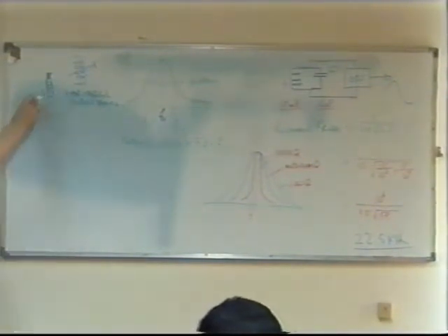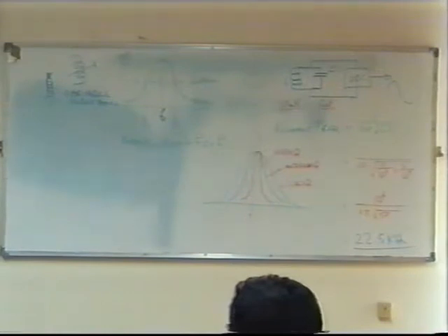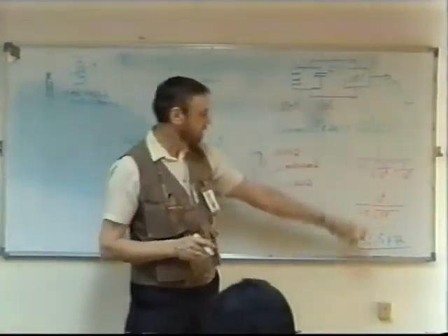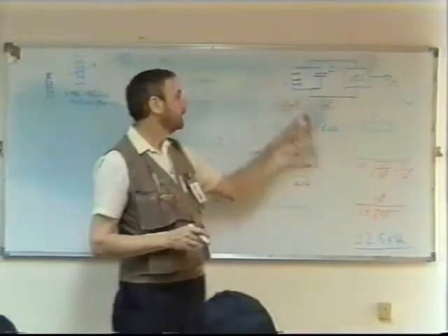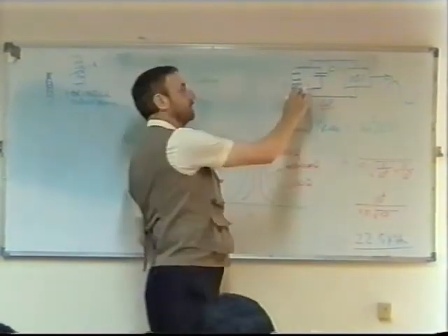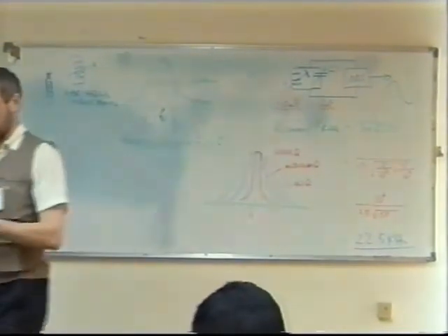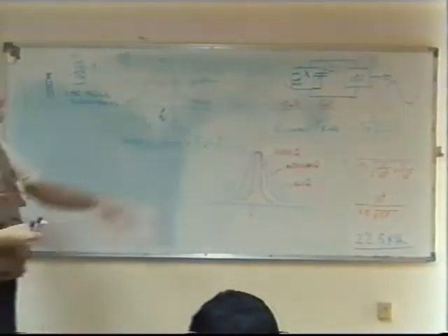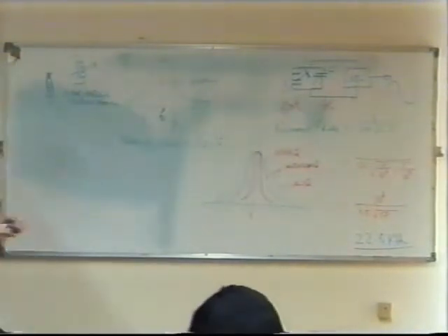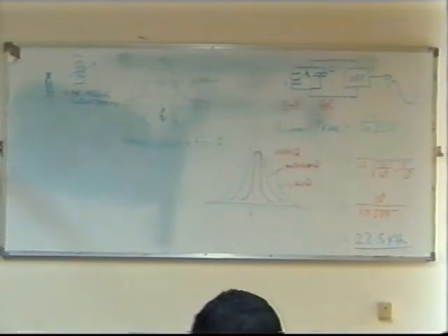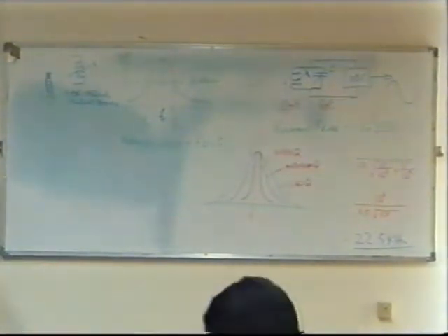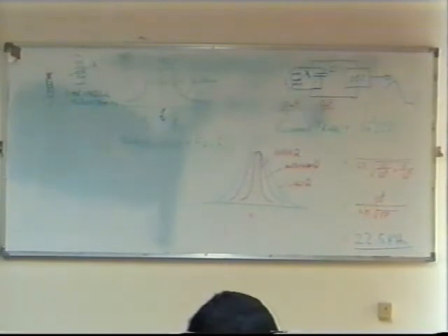Why do you think it's necessary to be able to change the value of L? Just exactly at the frequency you want. That's right, to get it exactly right. When they design these circuits, they want an exact frequency. So instead of just using fixed values, we could make one of them, or maybe even both, variable to a certain extent. But very often it's the inductor that's changed, so that they can adjust it to an exact value of L, to give them an exact frequency of oscillation or bandwidth or whatever.